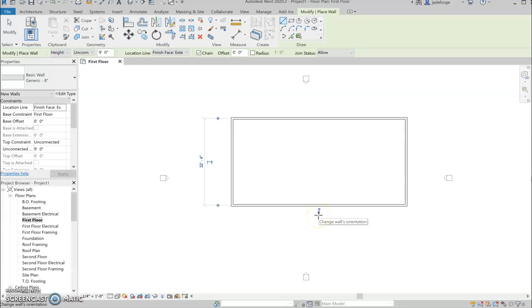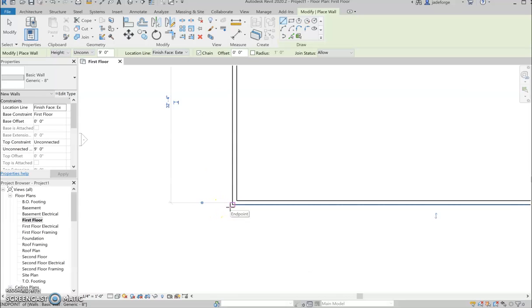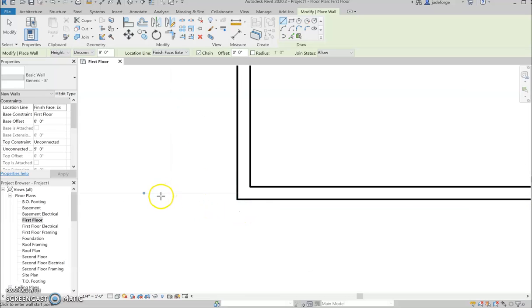So the arrow is going to indicate the exterior part of the wall. So again, I'm going to get rid of these. Another thing I wanted to point out is you can see these dots right here. These are moving the witness line. So that means this extension line, if I zoom into this corner, is actually coming to the center of the wall, isn't it? And when we do dimensions in the residential world, I want it to the exterior part of the stud.